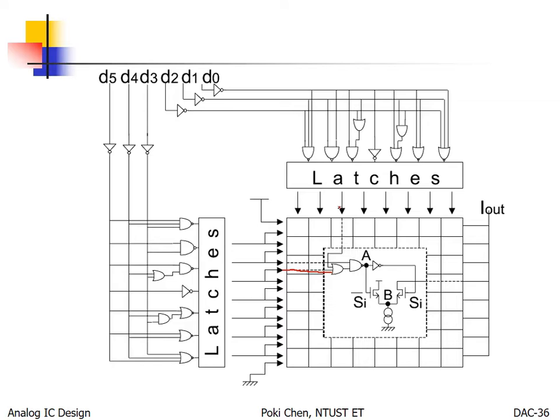And that is one of the outputs from the column decoder. So whether or not you would like to pass the control to the column decoder depends on myself. If I'm 1, I will turn all the current sources on here. You will get 1, right? If I am 0, then I will pass the control. So the output will be 1 if the column is 1. Or if the column is still 0, then you get 0.